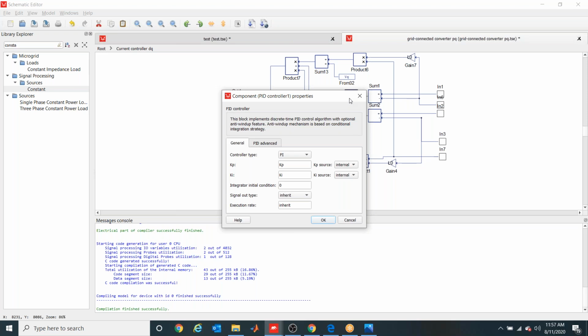Okay. But I have a HIL device. We have analog channels in there. So I will design my controller in dSPACE, which is a very fast controller. So even if I don't discretize it, it's running at a very high speed. So can I use analog pins on the HIL device and use KP, KI as they are? Yeah, you can use that also. But in general, are these KP, KI discrete values, or are they the normal KP, KI values that you find using Bode plots, root locus or the Ziegler-Nichols method, any method that you use?